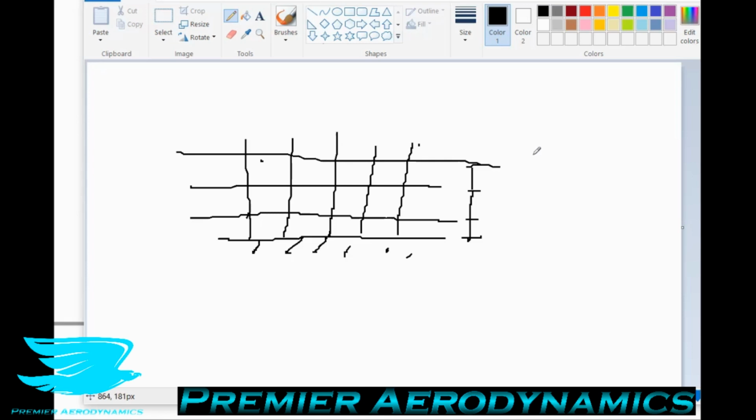Why do we do this? Because there can be problems between matching the LES and the RANS halves of the simulation. If we are still inside the boundary layer and we go from RANS, let's say we have RANS here, and then we go to LES here, there may be some properties which will then just start to trigger errors in the data that we're calculating between these two cells, which will then result in the simulation crashing.